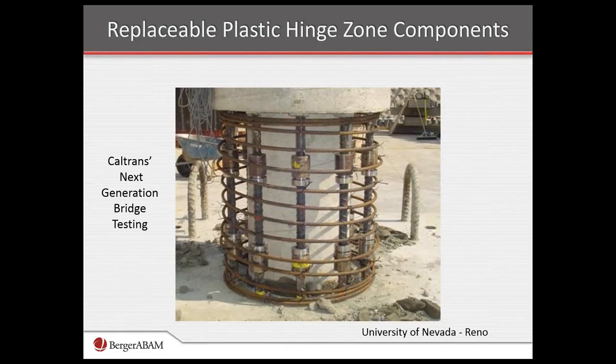This is a precast column, and then the outer shell is cast after placement of all the steel here. One of the challenges, obviously, with this is we have tight tolerances, not only in the cross-sectional dimension, say X, Y, but also in the vertical dimension of tolerance of the length of those bars and the placement of those couplers. So this is potentially something that could come down the pike, or a variant thereof eventually. So this is in the emerging technology realm.